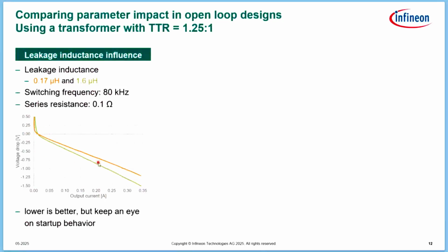And this is basically why we selected, for the transformers we provide on the evaluation board, one with a higher leakage inductance, because it gives us the better startup behavior so that the customer doesn't need to consider that from the very beginning.